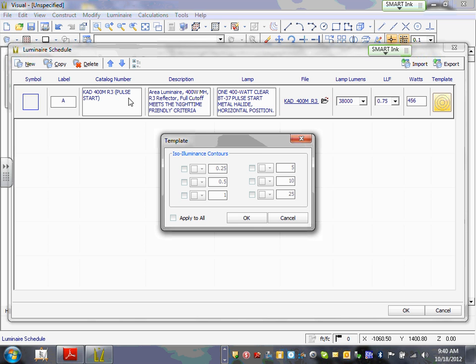So can you guys go here and click the ISO illumination control right here? Can you click this one here? I want to know the 0.25 and 0.5. Well, let's do it at 0.25. I want to know the cutoff. No, actually, because we're saying the minimum is 0.5, I'm going to put 0.5. Why 0.5? That's the cutoff. At 0.5 is my minimum. Anything less than 0.5, I want to put more light on it. Okay, the cutoff is 0.5.